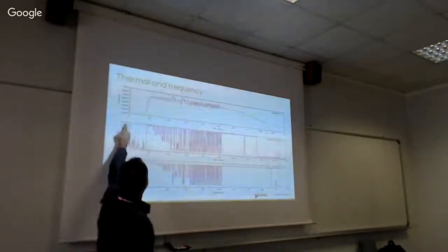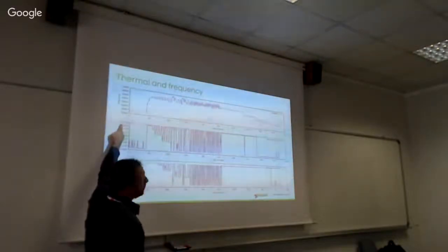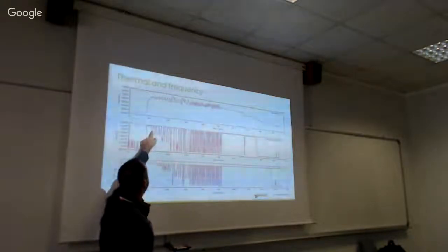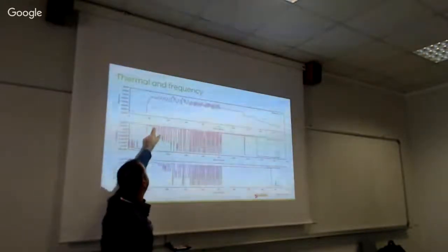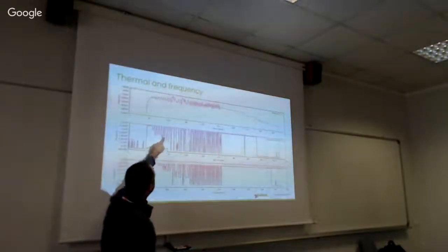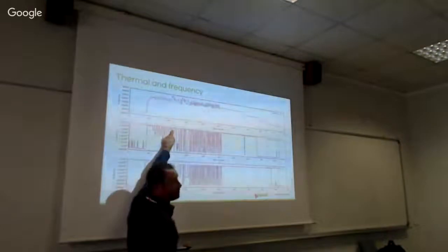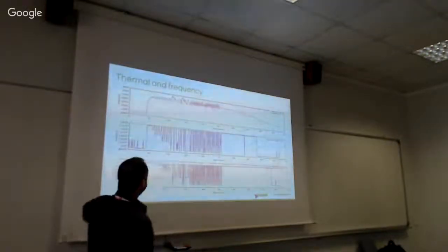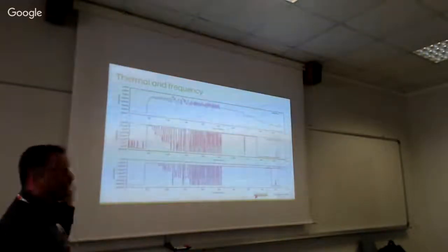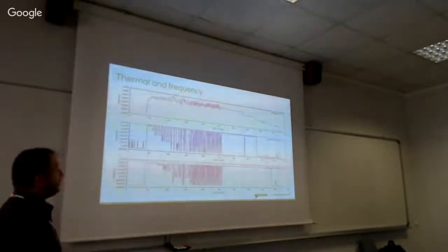So we see that at the beginning we are jumping from 2.4 gigahertz to the OPP just below 2.2, and then we go from 2.4 to 2 gigahertz, and then we have big changes from the highest OPP to the lowest OPP. And that's the way the CPU cooling device is mitigating the temperature on the circuit.